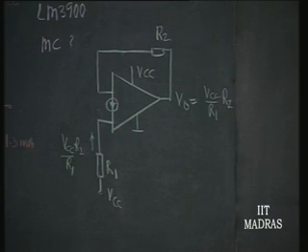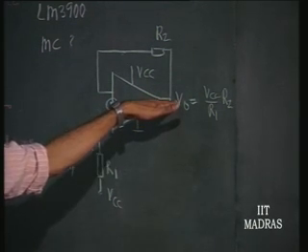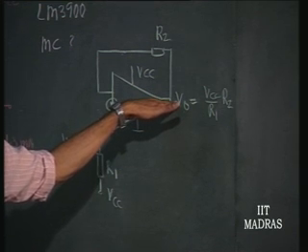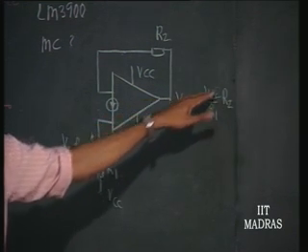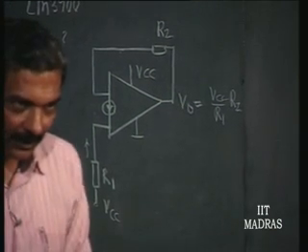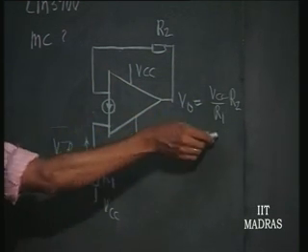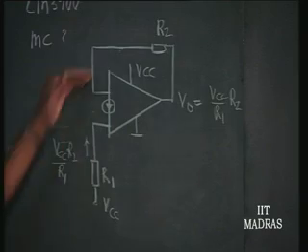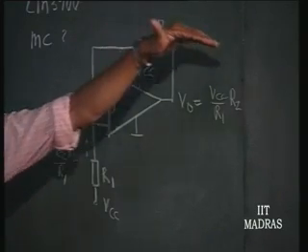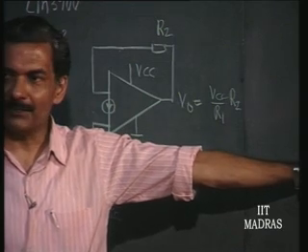So, you can make the bias point at any point you want as the quiescent point. If you want it to be half, you can accordingly select this. Now, apply an AC signal, capacitor coupled obviously, so that you can inject whatever current you want into it. Then the summation of all those currents will flow through this and appear as signal current at the output. You can extract it again by decoupling it by means of a capacitor.